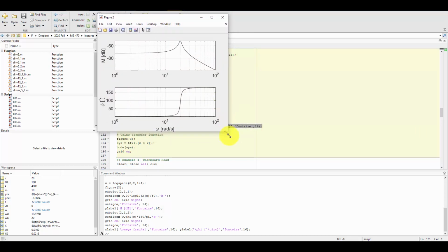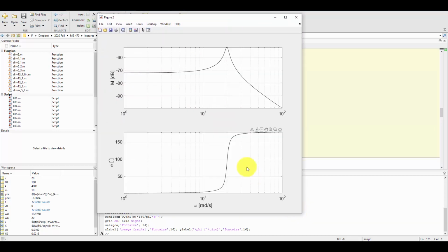And this is the figure that comes out. So like I just said, really all this is a Bode diagram. Now, the Bode diagram we made differently in system dynamics because we went into the Laplace frequency domain and then were able to construct it, well, let MATLAB construct it for us automatically, but we had a slightly different way of figuring out that magnitude and that phase. This is showing that exact same thing that we get from letting MATLAB make the Bode diagram, but from this analytic method in the time domain.